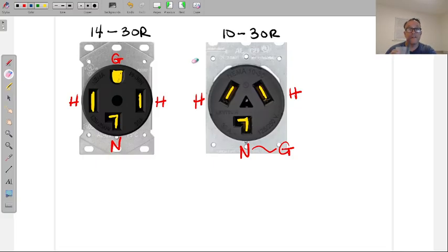Now, this is the same for the oven. That's why I don't have the oven here. It's just the same 4-wire situation, 3-wire situation. And I really don't know why, I guess I know why the code book did it. They wanted to provide an insulated neutral to the, again, lower impedance path to ground is always best when possible. So 4-wire, and I don't even know what year it happened, but 4-wire became the standard now.